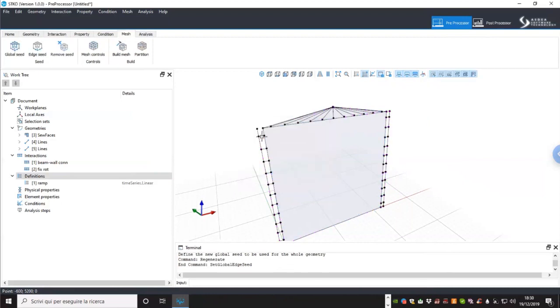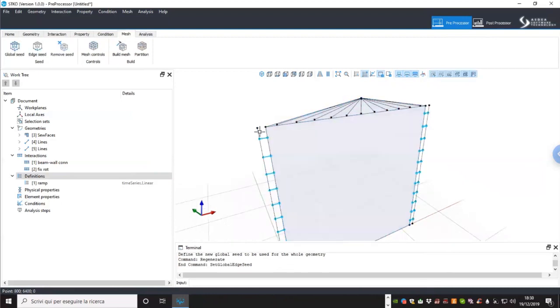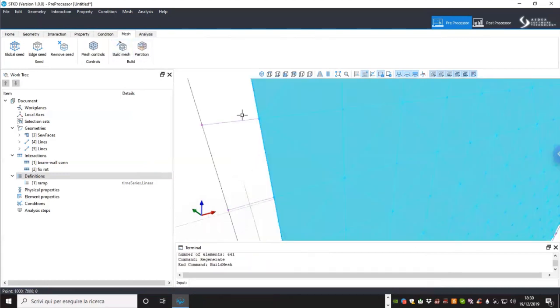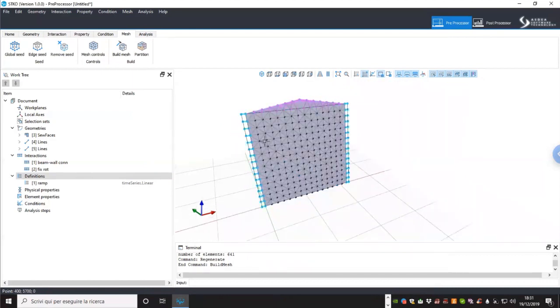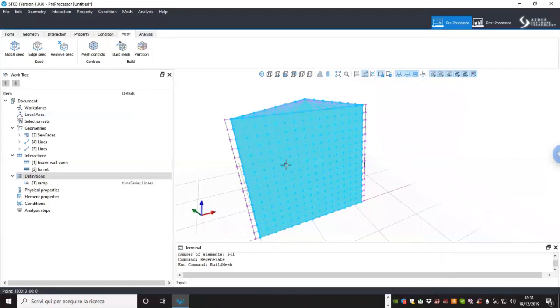Done. Now, when I mesh the model, you will see that this connection will be located actually in the position of the nodes. So this is the advantage of using this distributed approach, because in this case, the connection, which will be node-to-node connection like equal dots or zero-length elements in OpenSees, will be automatically located at all the nodes along the geometry that you created.